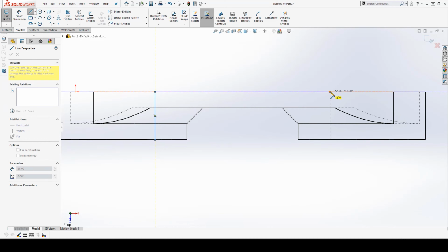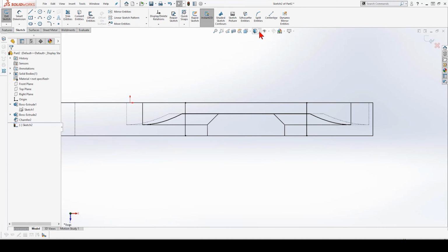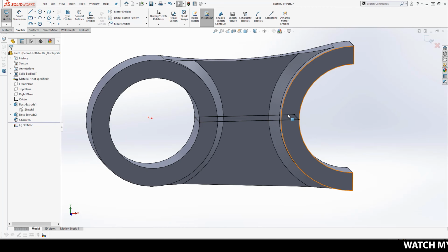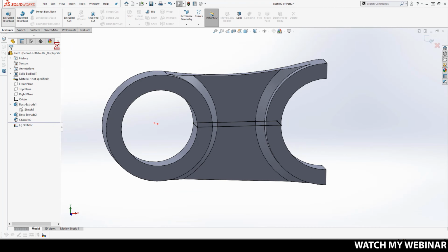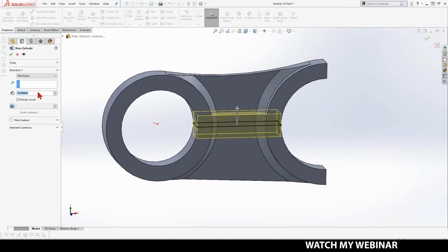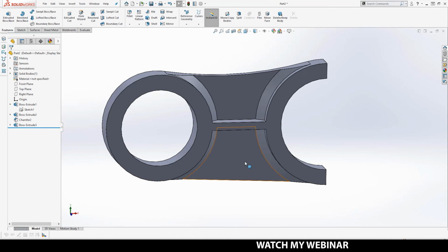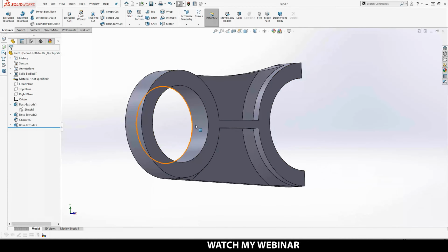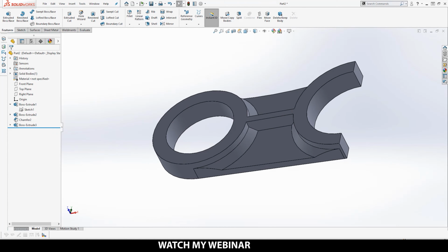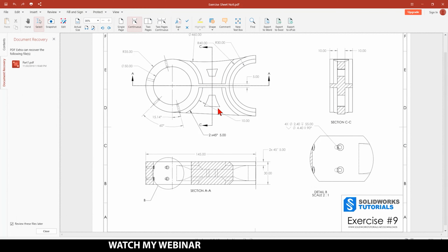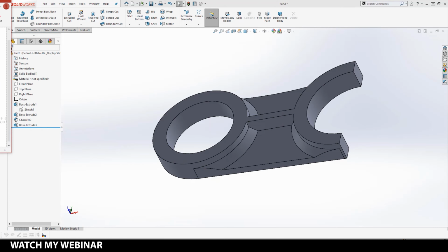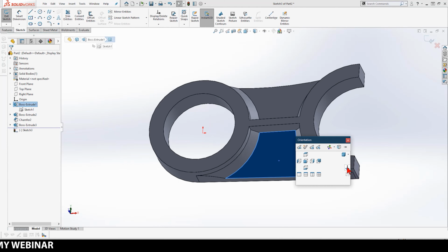The reason I do that is if I start drawing on the outer lines, the outer contour of the component, I'm going to face some zero geometry issues, and that's why I'm going to place the inner lines of the wall onto the component so we don't face any issue with that. 5 with midplane because it's in the middle, and done. So you see there is no edge here, there is no edge there, it looks fine. We have two cavities over here which are created using offset, value of 10 for both of them. So it's easy, you just activate the drawing on this plane.